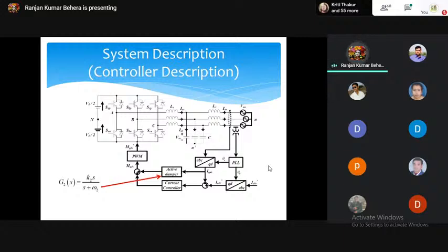So to control this resonance and to get high performance, we have added another path in parallel to the current control, that is called the active damper. In the damper circuit, I think all of you must know, in a synchronous motor there are damping windings. What does the damping winding do? It damps out the oscillation. So how does it damp out the oscillation, for a layman, how would you teach that?